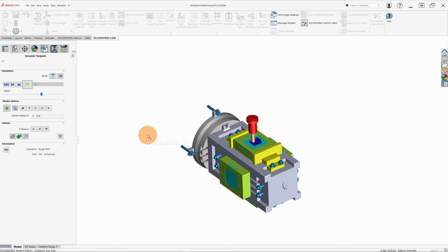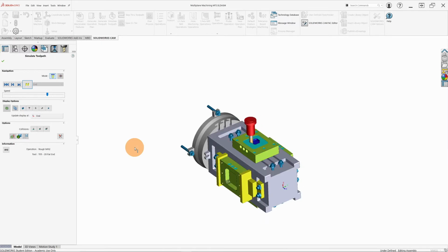We start off, we have a roughing operation on the pocket, and that should be followed then by a center drill operation for the holes. Tool change, that's our center drill. You can see we're center drilling and drilling the holes, and after each part that can be machined on that particular plane is finished, then we rotate the tombstone 90 degrees and it continues the operation.